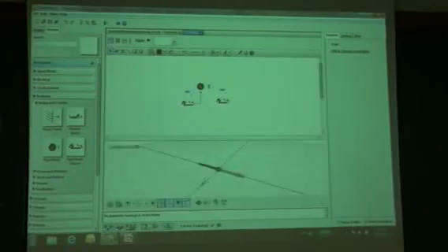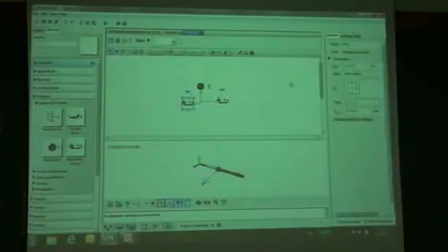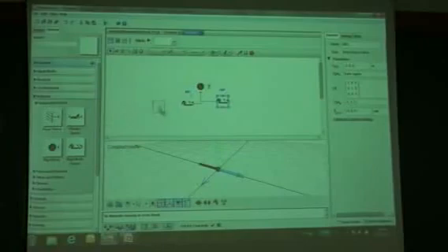Something else I've got to put up here is, for the multi-body components, you have this visualization tool that allows you to view what you're doing as you're building your component. These body frames are used to define, in this case, the distance between this point and this point to be 1 meter in the x direction. I've done the same for this, and we can see that appear in here. What I also need to do is put a fixed frame in here.